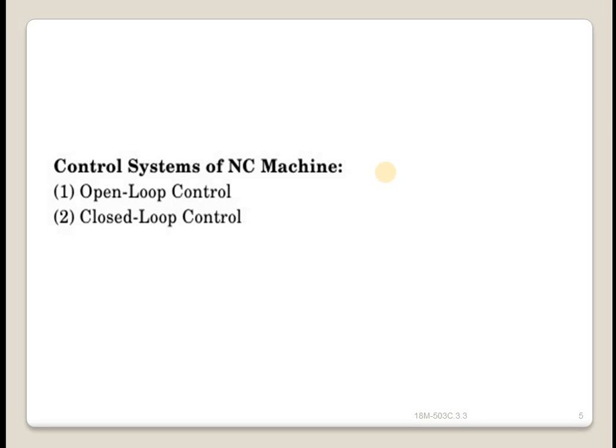Because stepper motors do not require feedback hardware, the price of an open loop system is much cheaper and simpler than a closed loop system. So the drawback of the open loop system is that there is no feedback to the controller. If the motor does not operate as instructed, there is no way for the system to know. The controller system will continue performing the next task as if there is no problem until a limit switch is tripped or the operator resets the machine.